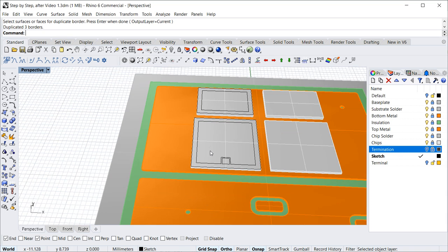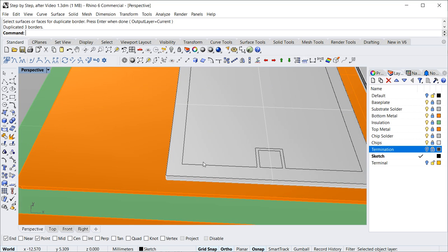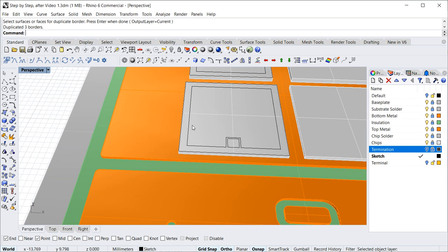So we want to place bond wires from the diode over the IGBT to the substrate metallization here. And in bond direction we need to keep a safety distance of maybe, let's say, 1.5 millimeters, and in the other direction here to this border of the bond pad we want to keep 0.7 millimeter.